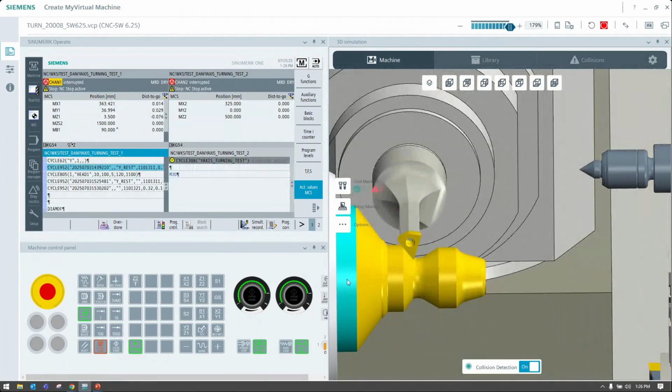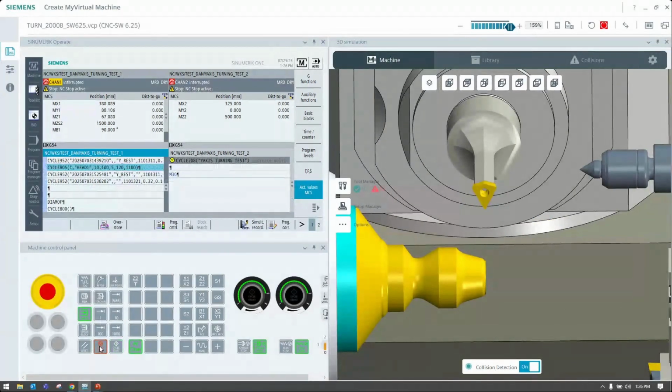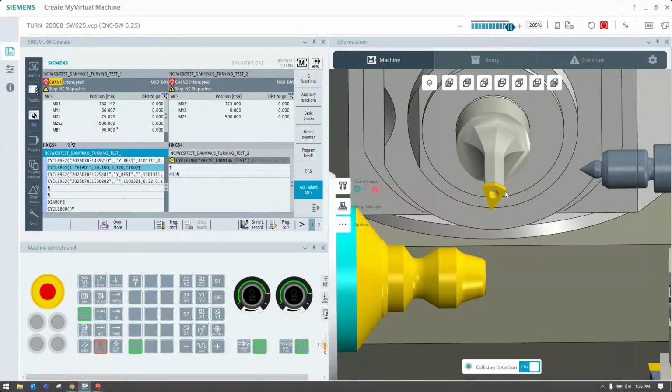And then again, I have some contour here, and this is kind of like your left-handed tool. Yeah, so we kind of have a left-handed. Now we've got to change direction so that I can actually finish this, right? So now I was at like a right-handed tool. Now I'm at like a left-handed. So now I can go in and clean out the areas I couldn't get.